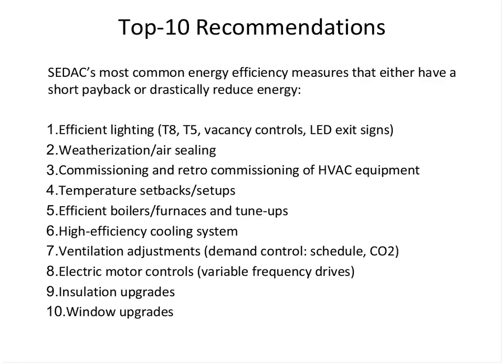We put window upgrades last. They tend to be pretty expensive. You're talking $40 to $50 per square foot of window, and it's a tough payback on windows. They're typically out about 20 years. So we kind of look at them last. But if you're going to replace windows anyway in a building, certainly put an excellent window in. You want windows with probably a U value now down to 0.25, which is an R4 window, and code requires that they be low emissivity, low E windows nowadays.